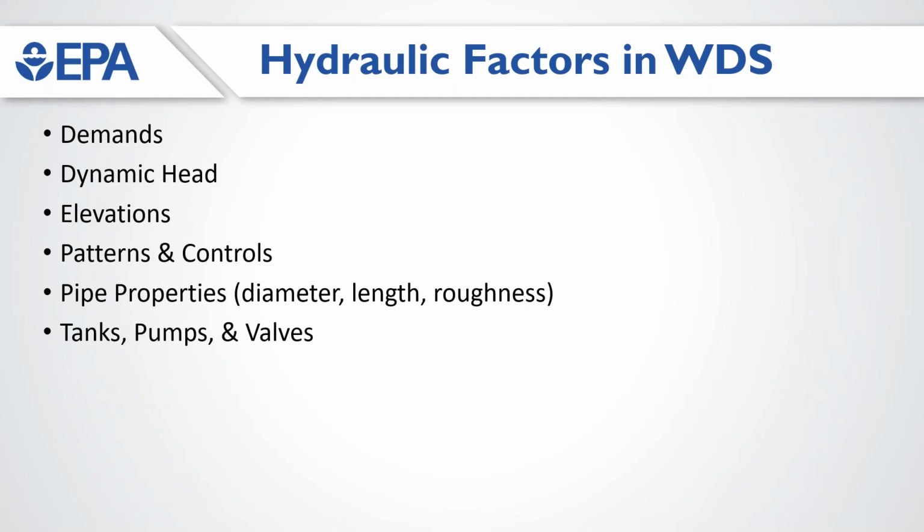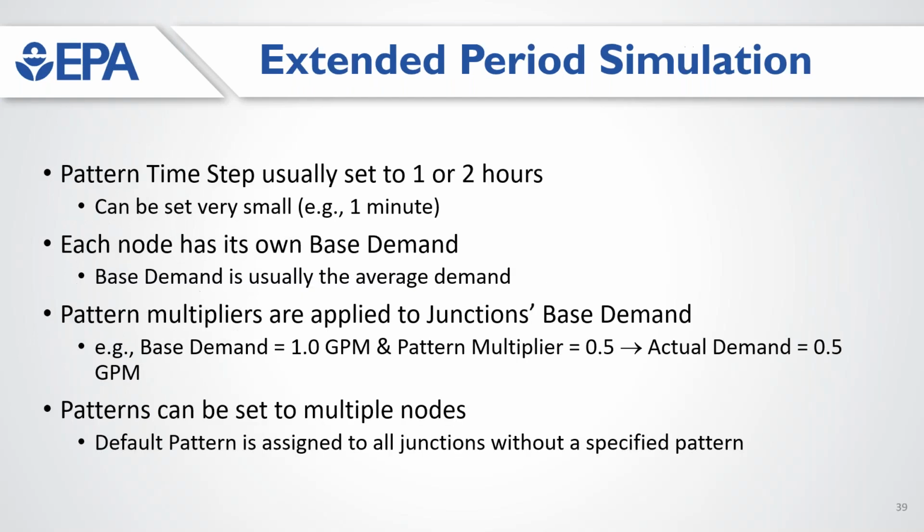And we know in distribution systems, tanks play a major role in order to provide a robust supply. So tank size, tank elevation, initial level, all this kind of information needs to be specified for tanks. And we also have a minor loss coefficient to accurately calculate the head loss in the system.